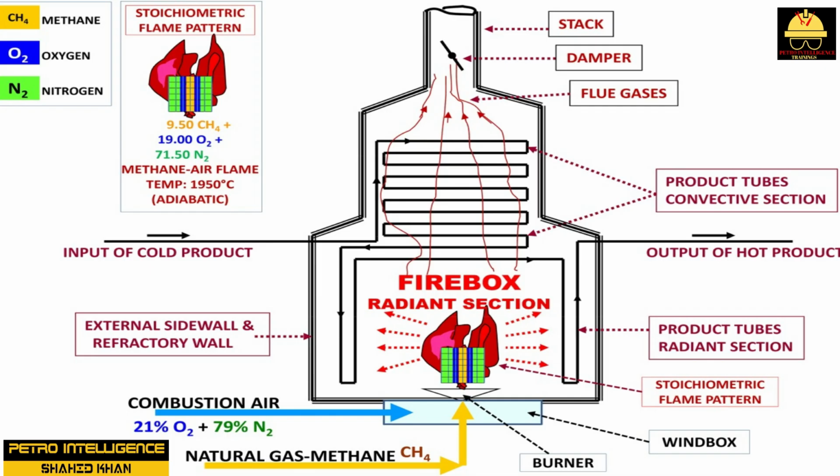Insulating firebrick has much lower densities, 27.3 to 78.7 pounds per cubic feet, and maximum temperature ranges between 1,600 degrees Fahrenheit or 871.1 degrees Celsius and 3,250 degrees Fahrenheit or 1787.77 degrees C. The refractory bricks are attached to stainless steel rods that are attached to 3 to 6 inch ceramic fiber insulation batt. The insulation batt and metal shell of the furnace touch. The insulation barrier between the furnace shell and brick prevents heat loss.